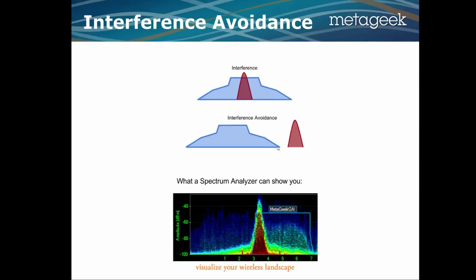Now someone asked, what is an automatic method to avoid or prevent interference? I really wish there was an automatic method to avoid or prevent interference. Now, some devices like your access points will have kind of an auto selection. Unfortunately, that auto selection is done by a Wi-Fi card. A Wi-Fi card does not have a spectrum analyzer built into it, so all it hears is other Wi-Fi networks. It could listen to a channel and say, "I don't hear any Wi-Fi," so that means it's good.